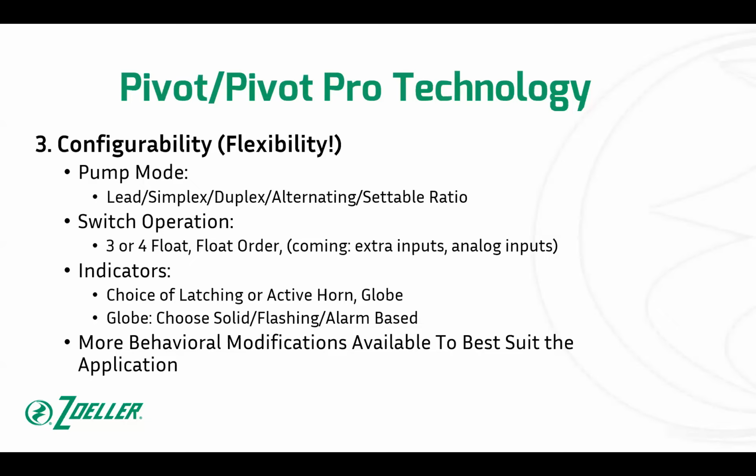You'd put that into permanent off, whichever pump is being worked on. And then that tells the panel to just operate as a simplex. So a duplex can operate as a simplex without creating alarms.